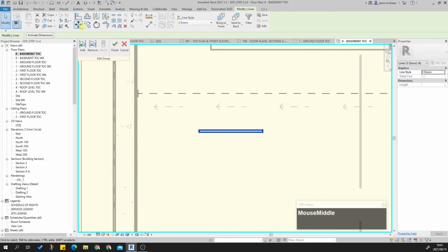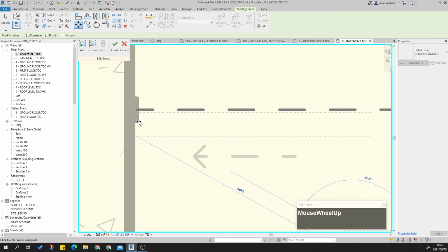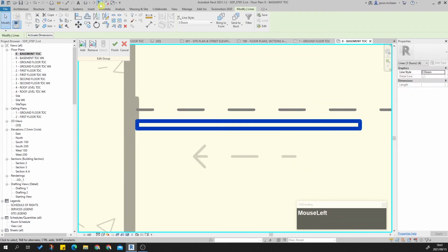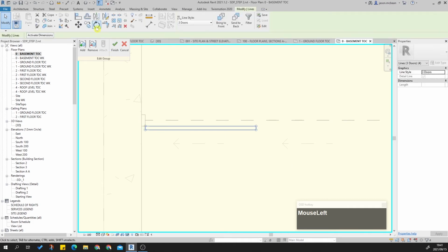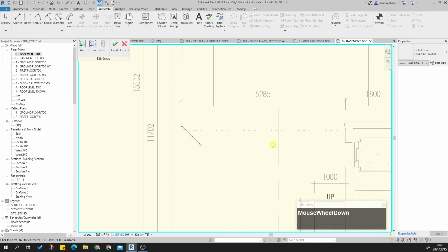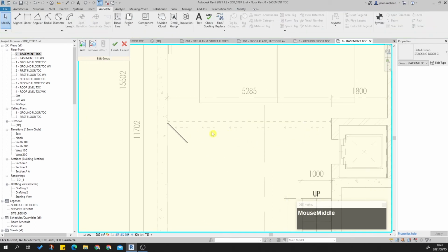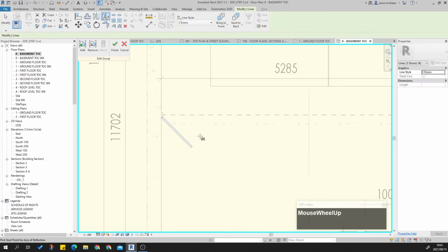So all I'm going to do now is move this over here. I've got a frame to work with. Just remember you can switch off your line weight so you get much clearer reference, and I'm simply going to rotate this by 45 degrees. Okay, so you can see it'll snap on 45, that's fine. So we've got 1, 2, 3, 4, 5, 6 panels. So here you're just going to simply grab that. You're going to use the mirror tool by line.